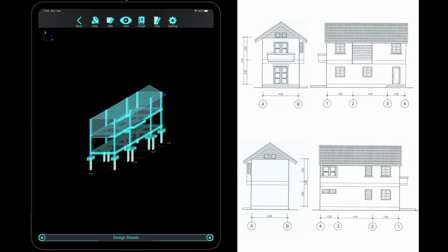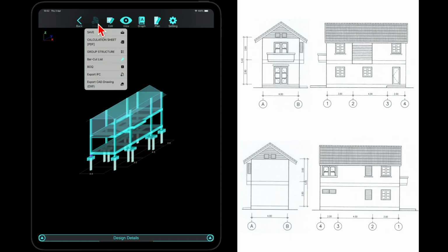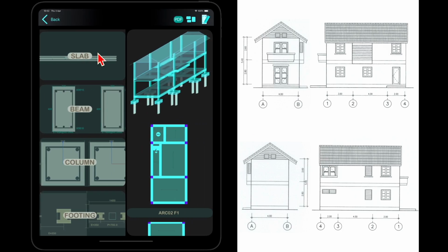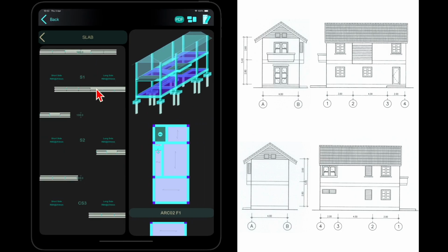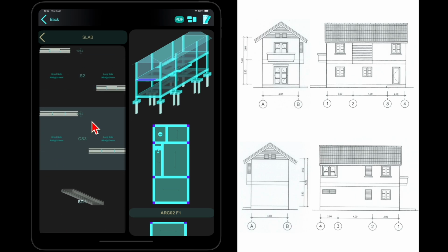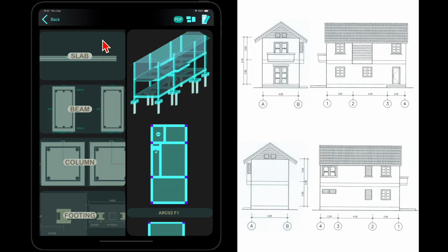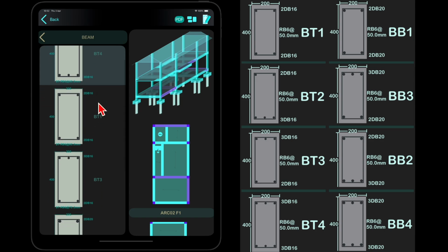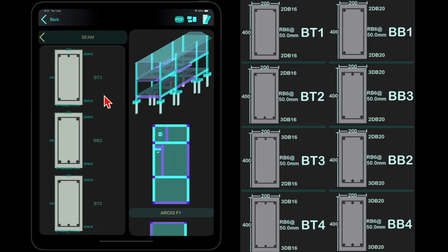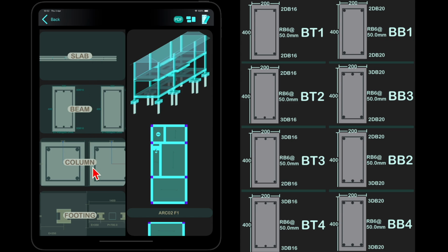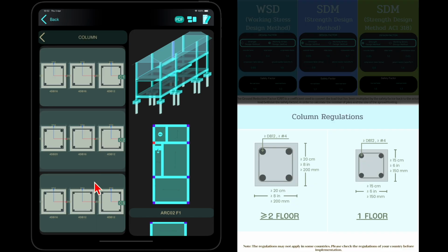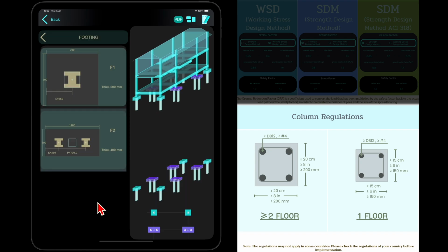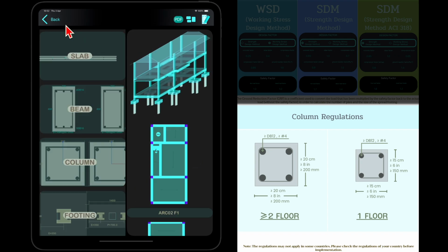Step 6. Analysis data and design adjustments. We'll start by reviewing the overall structural components of the entire building. Go through each automatically designed component to identify which ones require further modification. Most of the beam groups follow the intended design approach. However, for the columns, we'll standardize the rebar type across the entire building to maintain construction consistency and quality control.